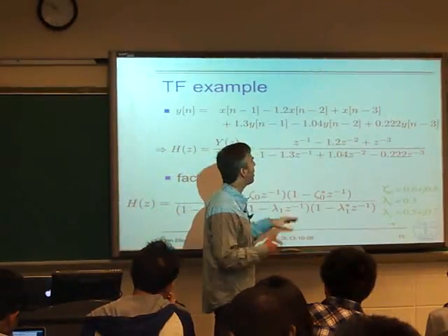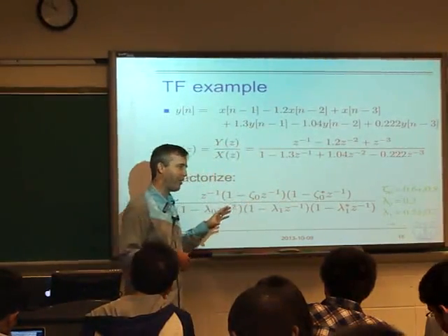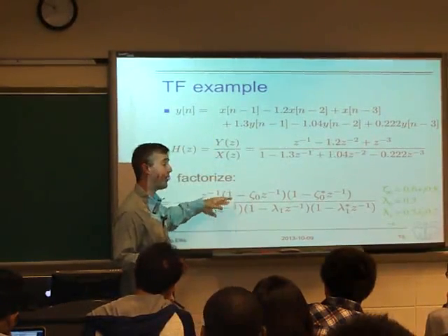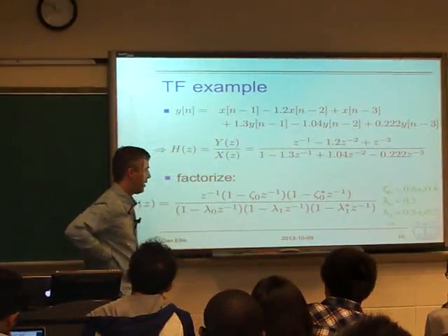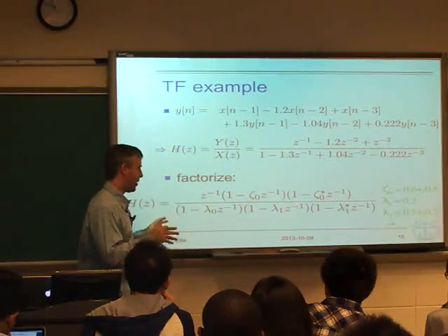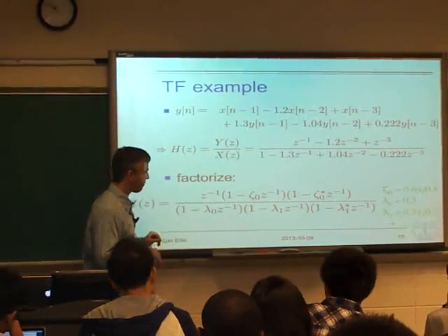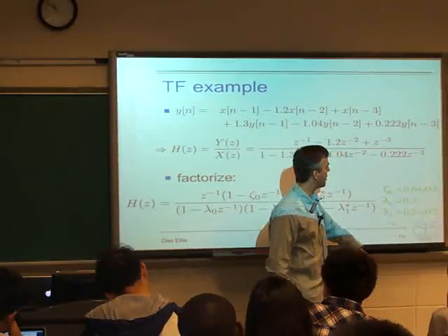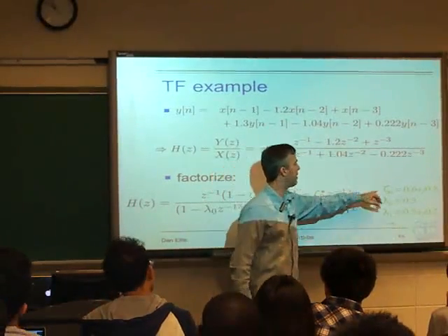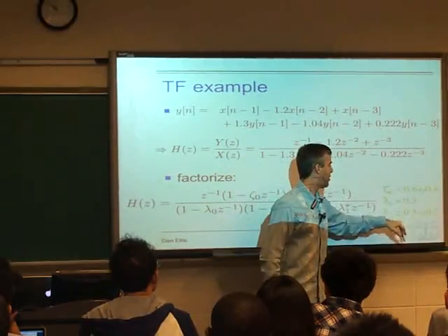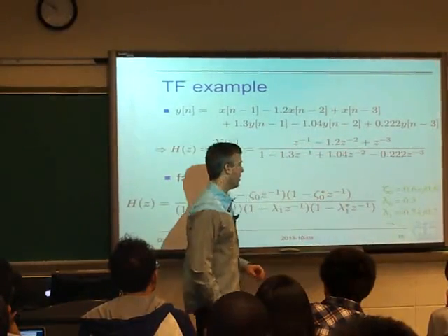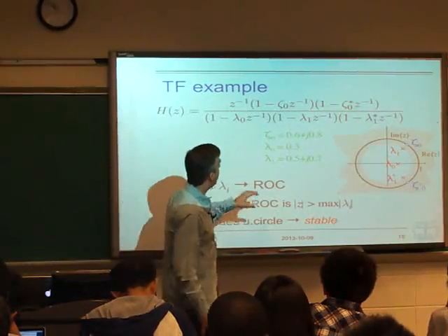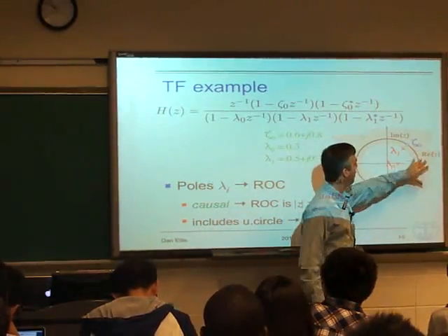But just to save us time, or to check that what we're doing makes sense, we notice that when we have these pure real expressions, we want them to give us systems that have pure real impulse responses. I picked these to have relatively round numbers for the roots. So we've got these two zeros at this and its conjugate. This is the real root, and this is the conjugate pole pair. So we can plot those on the z-plane like this.